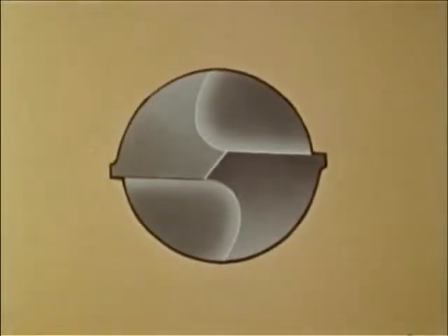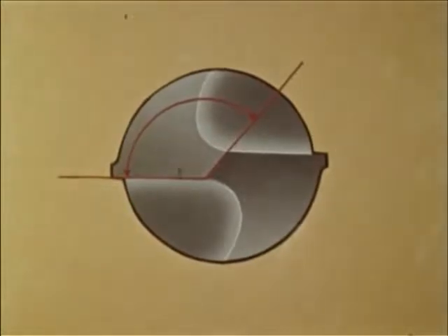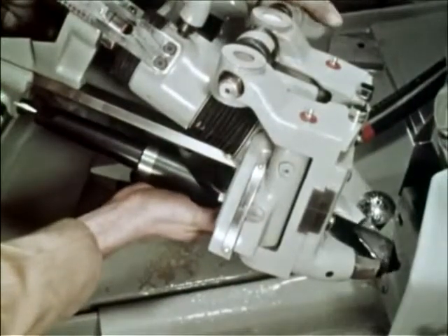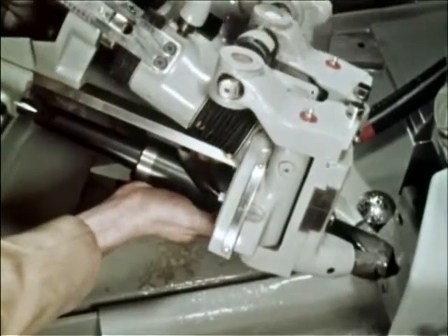A chisel angle of 120 to 130 degrees will ensure efficient entry into the work and minimize peripheral wear. Too great an angle will result in drill wander and bell-mouthed holes. Too small an angle will make the chisel, and therefore the drill, ineffective.